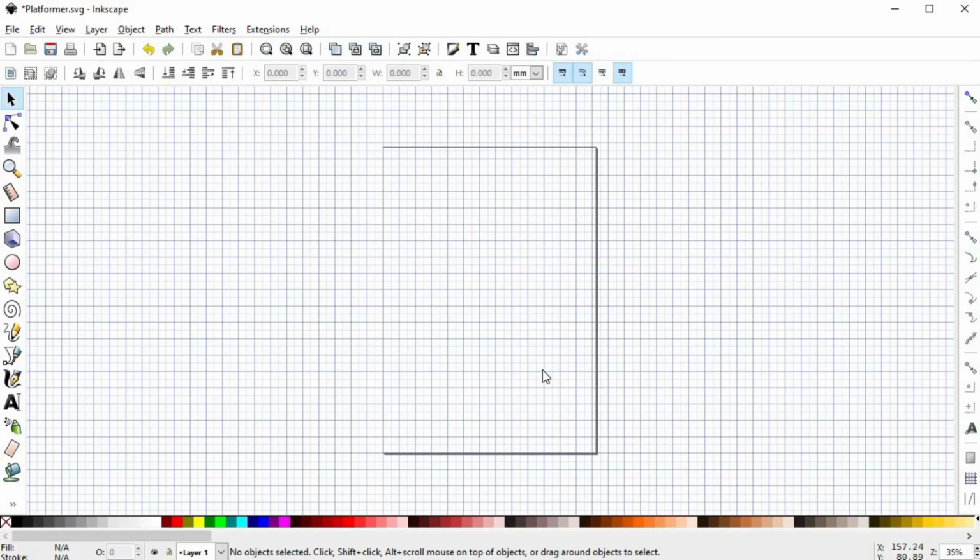First, of course, you need to enable the snapping functionality in the snapping options bar. Like I said in the Inkscape mini course, when you enable snapping, there should be a few options enabled by default. I recommend you not touch anything here if you don't know what each of these buttons do. However, if you want to be able to snap to grids, you should enable this little button. By toggling this button on and off, you'll enable and disable the snapping to the grids.